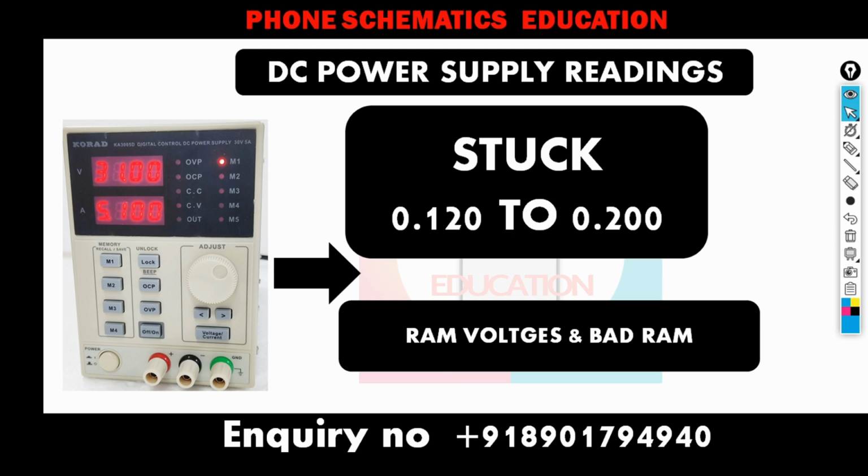RAM gets dry because RAM is attached with the CPU together in two layers, upper layer RAM and downward the CPU attached together. So sometimes RAM dries. So these types of issues are created. Also sometimes RAM is attached with the emergency circuit combined. Nowadays, in some phones, RAM is given separately by the companies. So if you see this type of reading, you can work on the RAM, complete the RAM circuit, the voltage requirements, the enables. Also, if there is a separate RAM, or on a double decker, change the RAM.